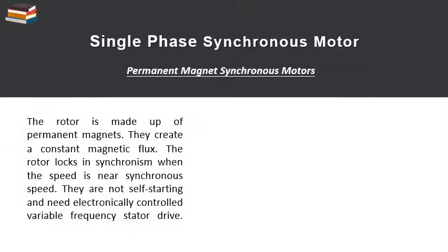The rotor is made up of permanent magnet. They create a constant magnetic flux. The rotor locks in synchronism when the speed is near synchronous speed. They are not self-starting and need an electronically controlled variable frequency stator drive.